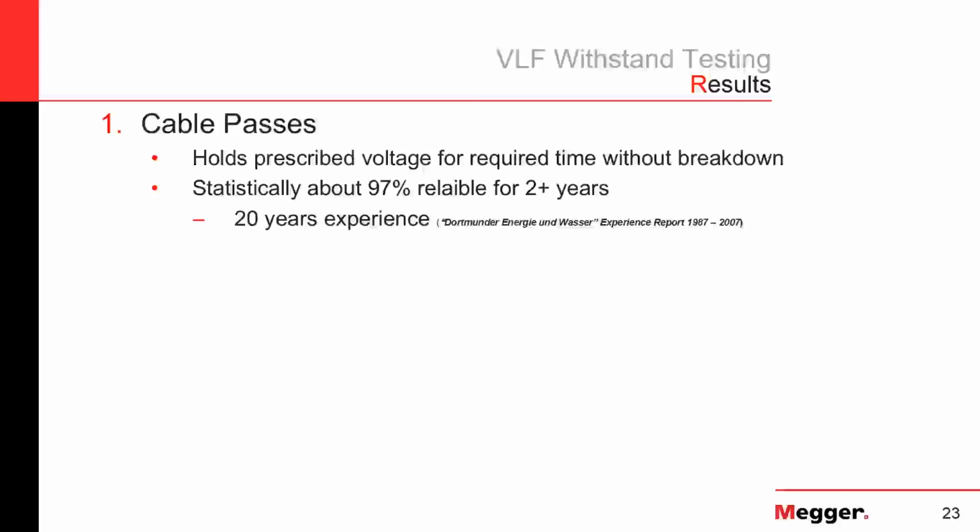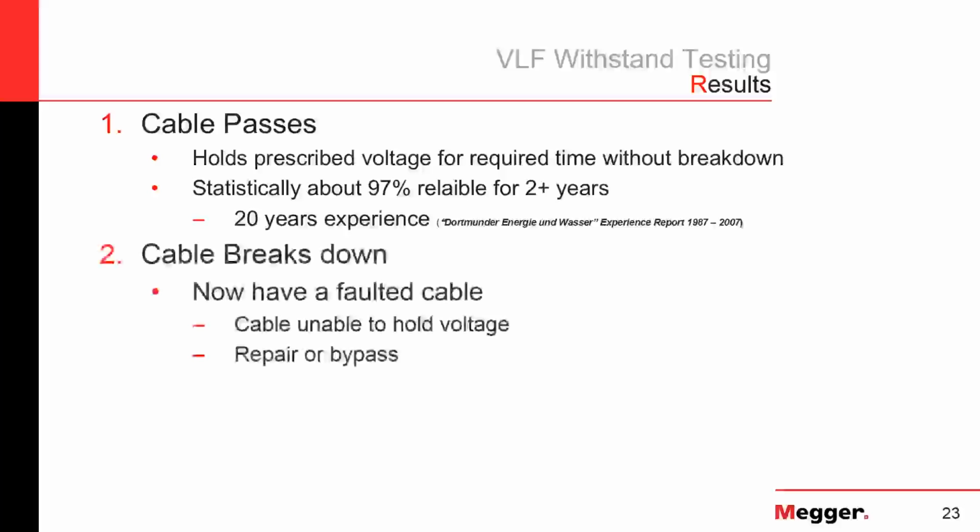So the results then: the cable can pass the test. In that case, it has held the prescribed voltage for the required time, and it has not broken down. Statistically, we find that that's about 97% reliable for the next 2 or more years. That's based on field results.